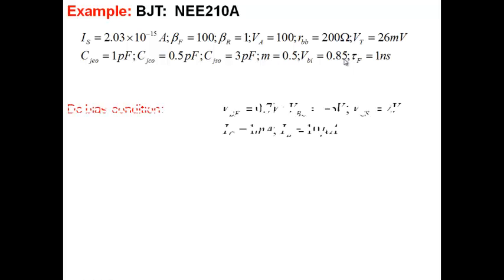Okay, so let's take this and suppose we use this particular transistor in forward active mode. VB is 0.7, and suppose collector base voltage is reverse bias minus 3 volt, collector to substrate voltage 2 volt, we bias it at 1 milliampere. Base current then is 1 milliampere divided by 100, which is 10 microamperes.